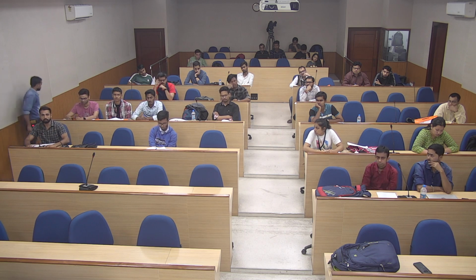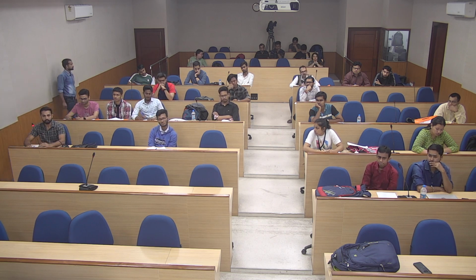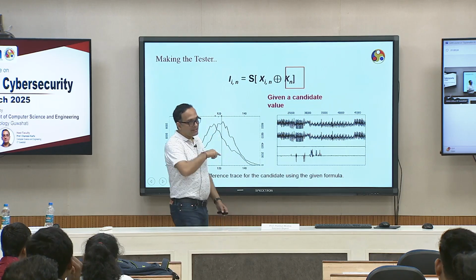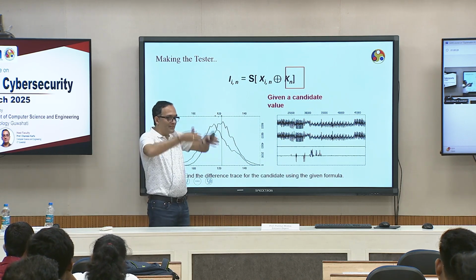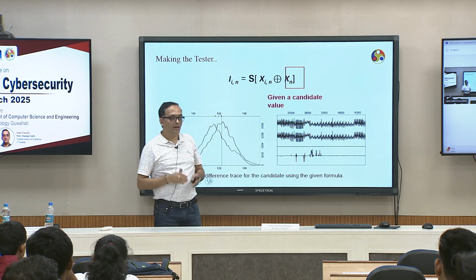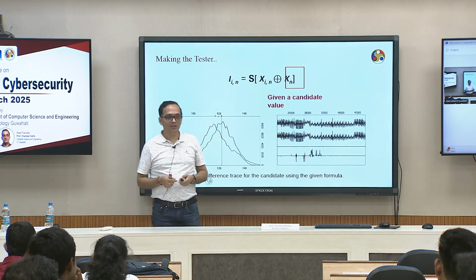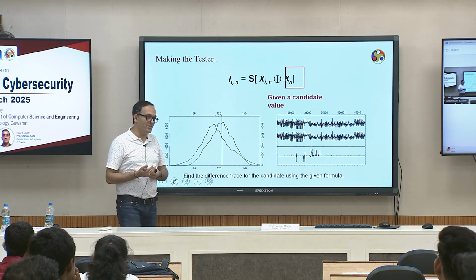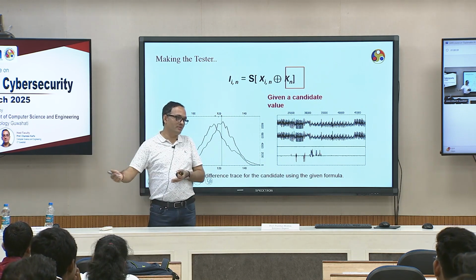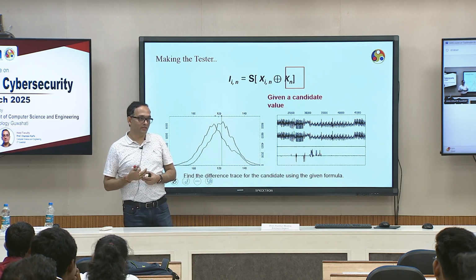You are in the physical proximity of the device and you are able to measure the power. Okay, so if you can measure, you will get the entire trace. You will not get only that part, but from the entire trace, you only consider the part which is interesting to you, and then you do the analysis. But it is possible specifically for, say, edge devices, IoT devices. An attacker can always get at them, and they can get the key, right? Right, sir.